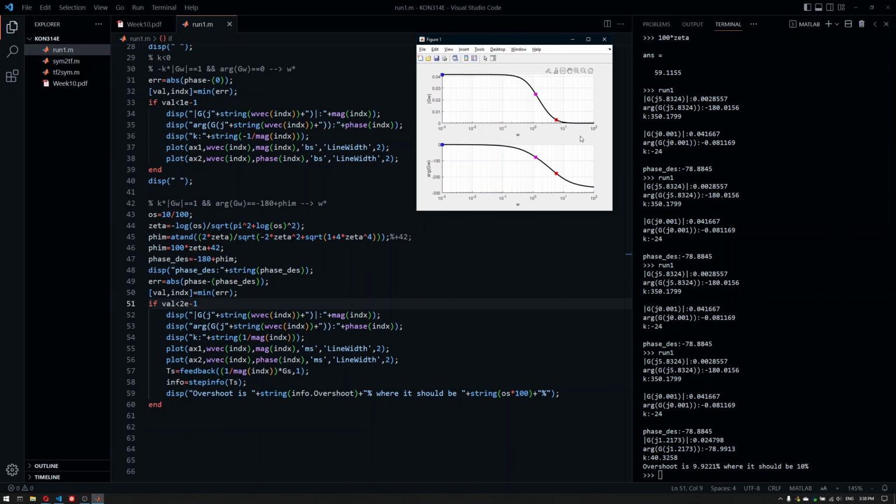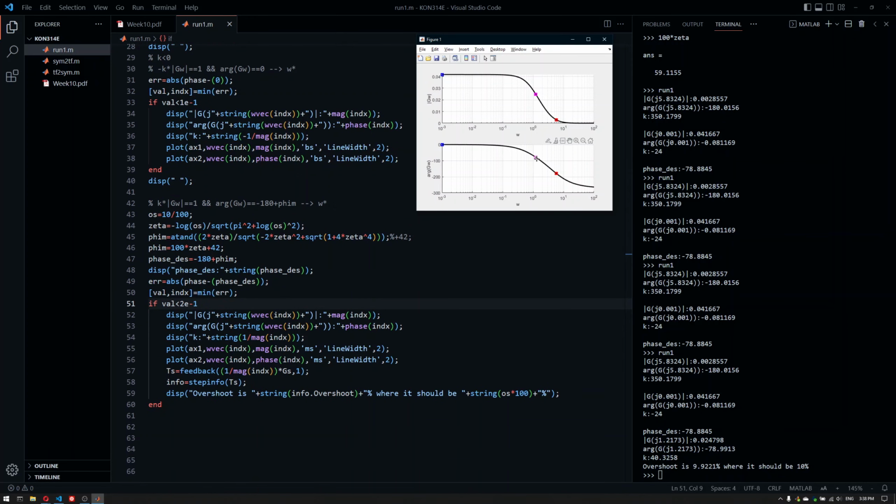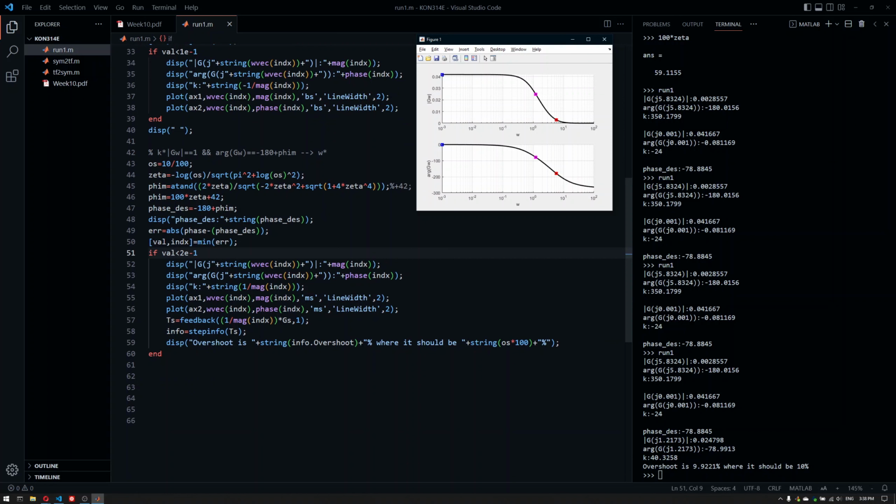For the stability parts, we have looked at these equations. For the design part, the synthesis of a p-type controller only, we've just adjusted the phase condition. We've altered it a little bit. We add just a phase margin, which we can calculate from a formula that uses zeta, or we can use 100 times zeta as an approximation. And sometimes if we are on MATLAB, we need to adjust it a little bit so that we match the overshoot here. So it's quite easy to design a controller using the Bode plot, because I'm just copying and pasting and adjusting stuff about it, and that's basically it.